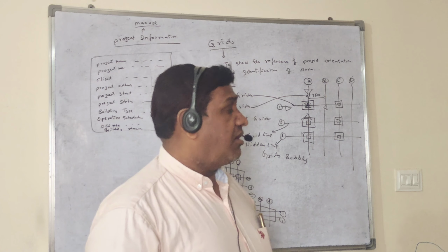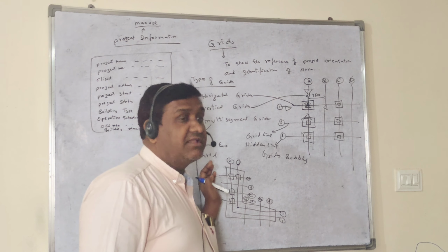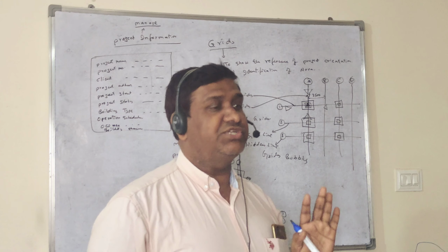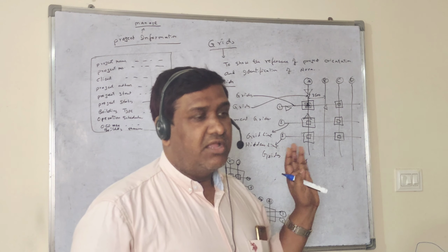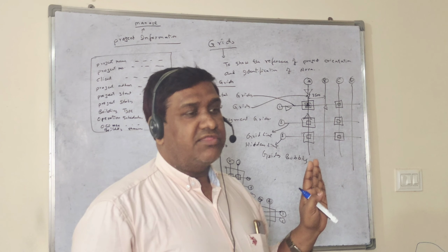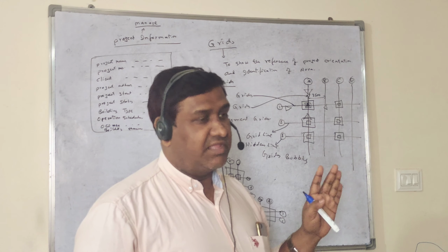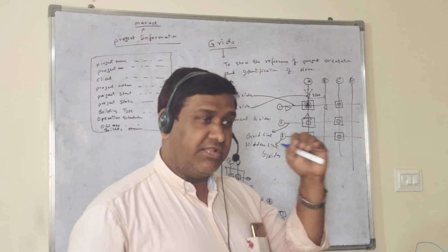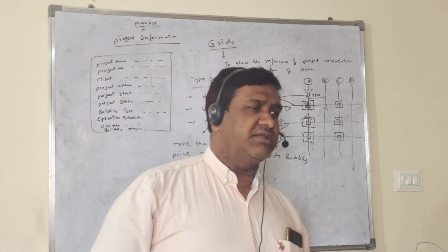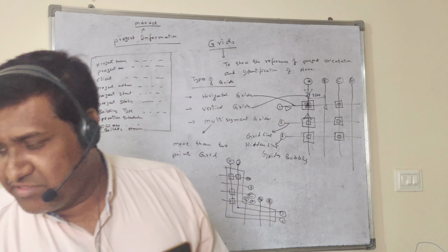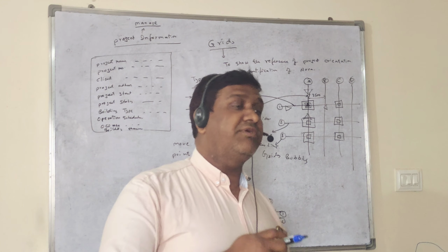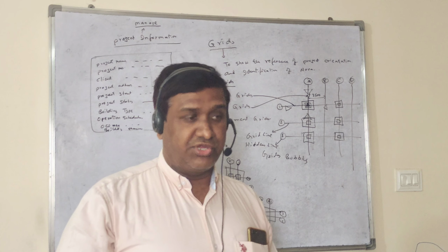That's the reason you always have to remember that when you are going to do any project, you have to fill in this project information palette fully. Once you fill it, it is never deleted. It will remain filled up to the end of the project. If you want to change it in between, you can change it, because sometimes the clients may vary, sometimes the consultant may change. At that time you can change it also, no issue.